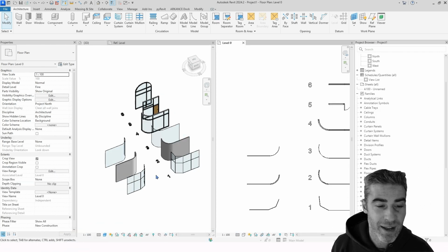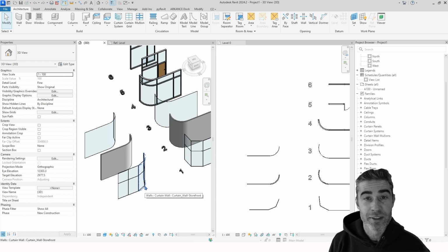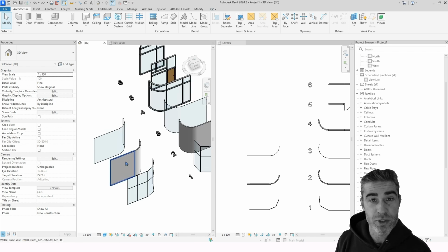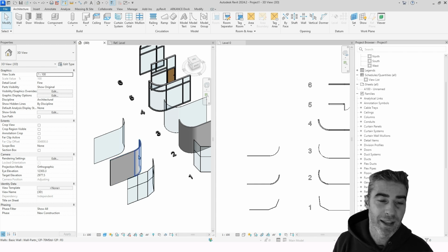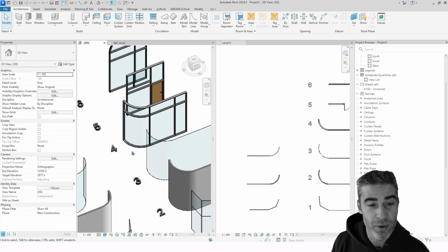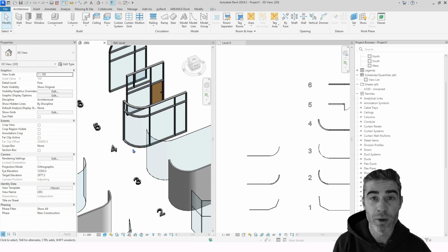Okay, so now that we understand that the curtain wall is going to create segmented parts, we know that a wall actually gives us more creativity and control when it comes to organic shapes and curves. And we kind of took the approach of, okay, well, let's strip down that wall to just a glass partition. But now how do we add mullions built into that wall? And before we do anything, and before we get to number 4 and getting it to look more like a curtain wall, what we have to do is create a profile. We have to create a profile of what our mullion is.